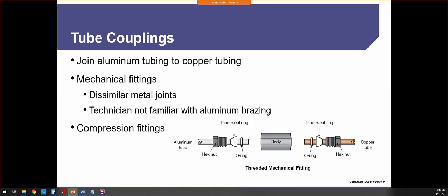There's also fittings out there called SharkBite. SharkBite is just a push connect. These little teeth inside there grab onto the copper and make a nice connection. So I can have this body, a SharkBite coupling. We would take the copper, push it in on one side, push it in on the other side, and I'm done. It's as simple as that.